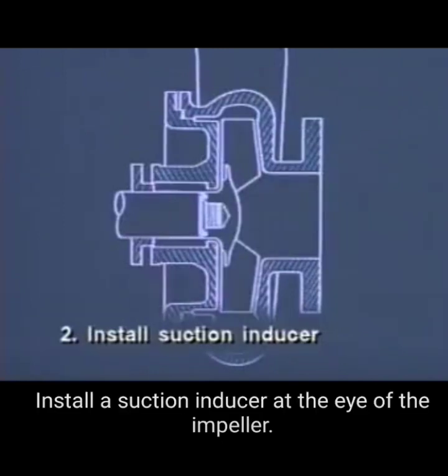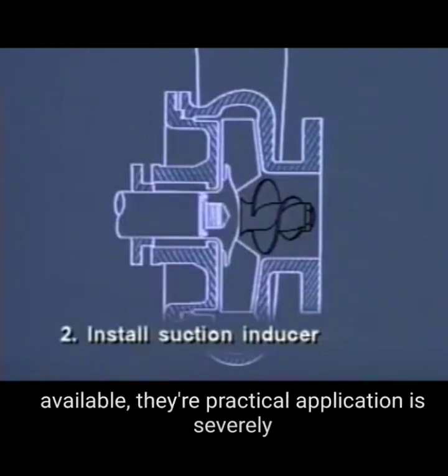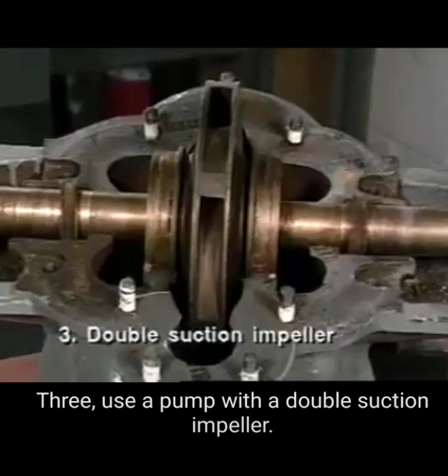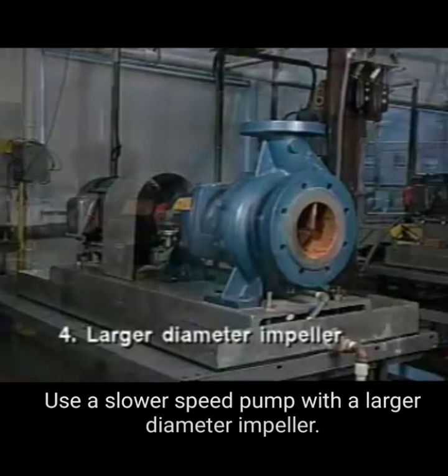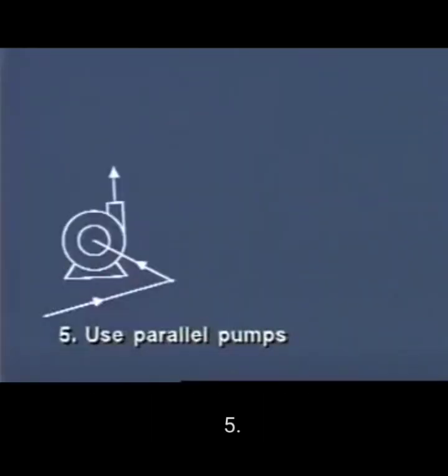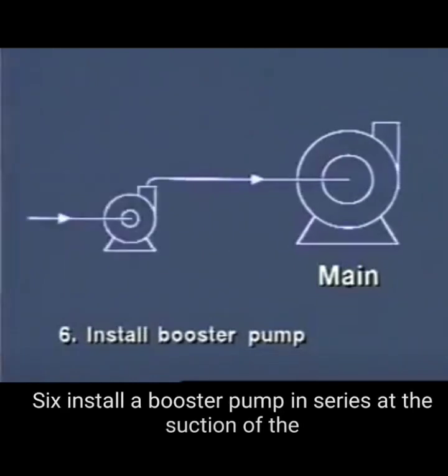2. Install a suction inducer at the eye of the impeller. As very few pump manufacturers have suction inducers available, their practical application is severely limited. 3. Use a pump with a double suction impeller. 4. Use a slower speed pump with a larger diameter impeller. 5. Use a number of lower capacity pumps in parallel. 6. Install a booster pump in series at the suction of the main pump.